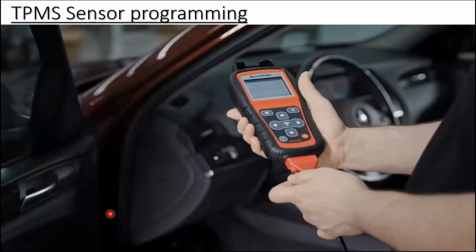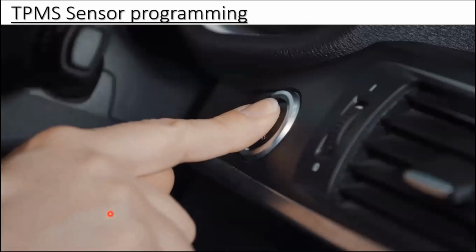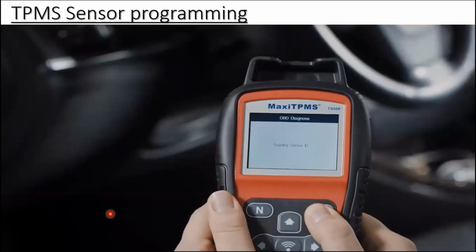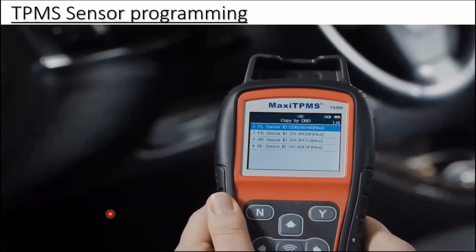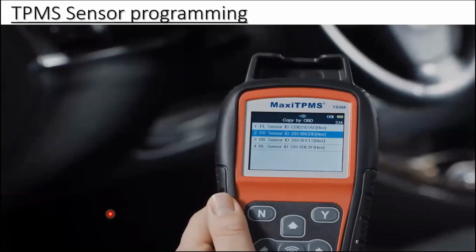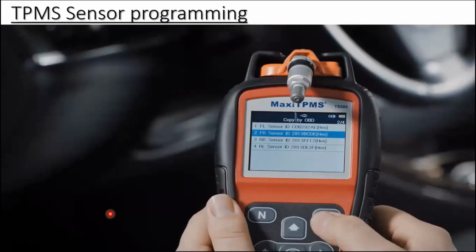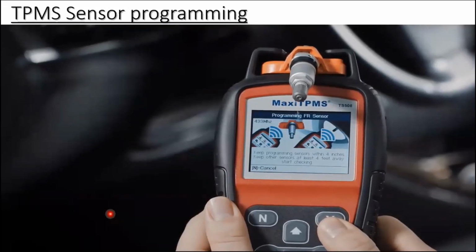Copy by OBD. Connect TS508 to the vehicle by OBD2 cable and turn ignition on. Press Y to continue. TS508 will automatically read sensor IDs from the ECU and display the IDs on the screen. Place the MX sensor near the top of the TS508 and select one sensor ID. Press Y to copy the ECU sensor ID into the MX sensor.